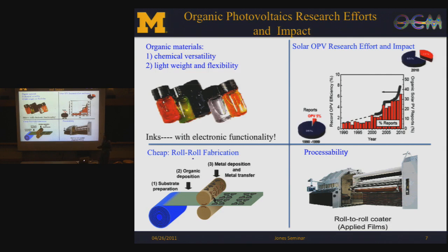Another thing for organic materials is that they have the potential for low cost of fabrication. Some organic materials have very good solubility in solvents. Then we can use very convenient thin film fabrication, like roll-to-roll fabrication methods. So in combination with the low cost of materials and the fabrication of thin films, organic electronics has a huge chance for low cost of production.